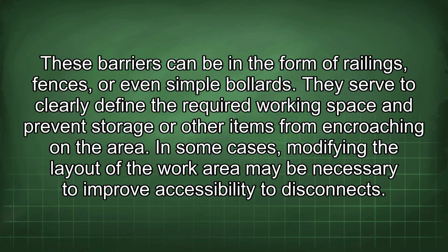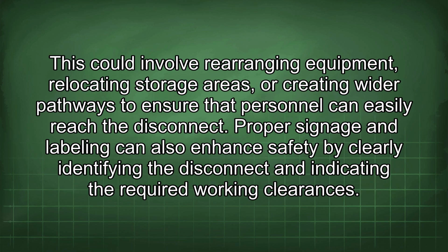In some cases, modifying the layout of the work area may be necessary to improve accessibility to disconnects. This could involve rearranging equipment, relocating storage areas, or creating wider pathways to ensure that personnel can easily reach the disconnect. Proper signage and labeling can also enhance safety by clearly identifying the disconnect and indicating the required working clearances.